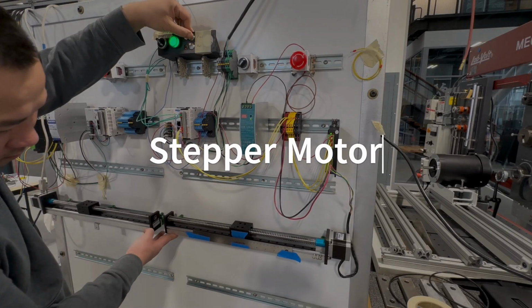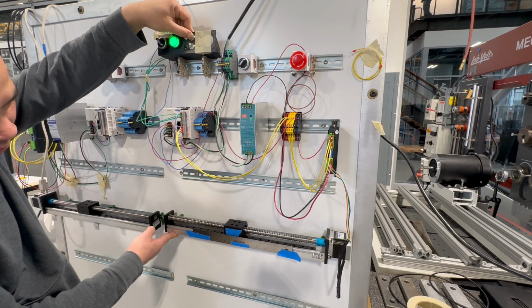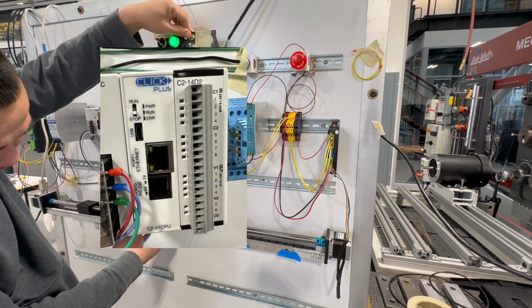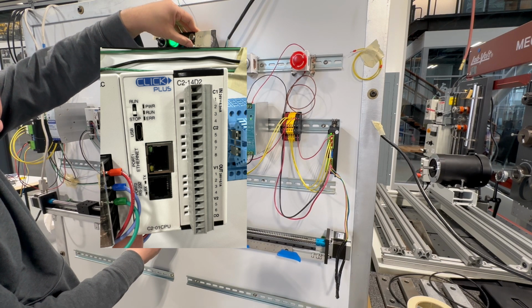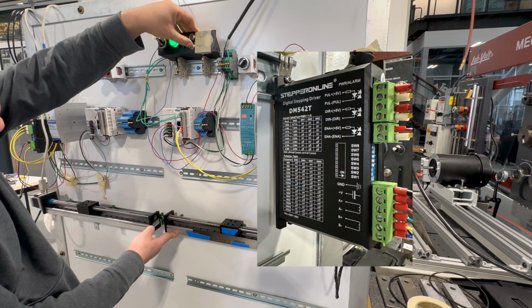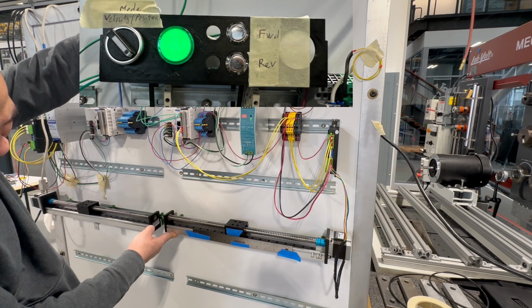Welcome back. In today's lab I will show you how to control a stepper motor and precisely move a linear stage actuator with a square linear slide rail. The components I used in this lab are a PLC Click C2-01 CPU and C214D2 module, a stepper driver DM542T, a switch for choosing velocity or position mode, and 2 buttons to drive forward and reverse.